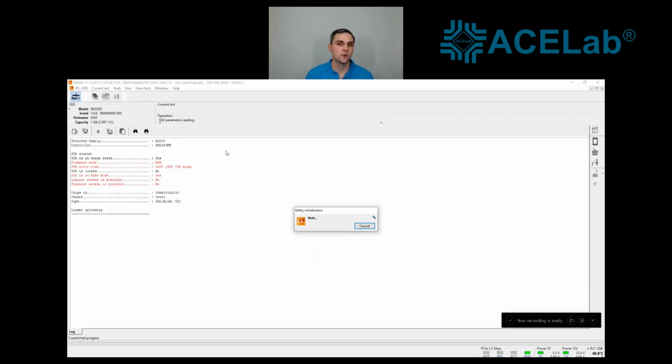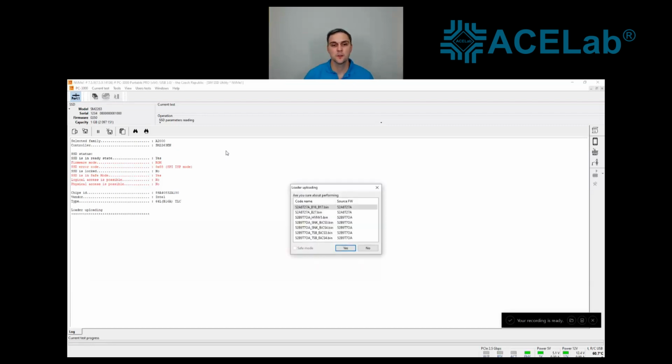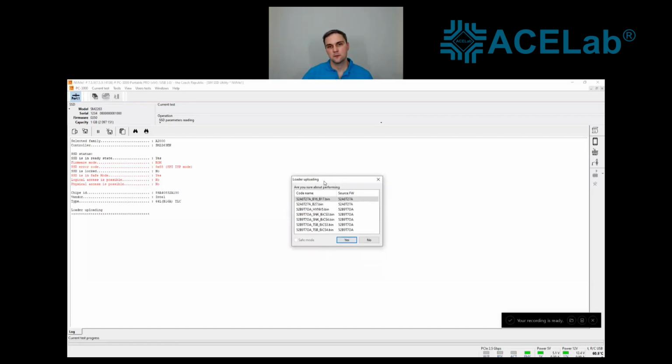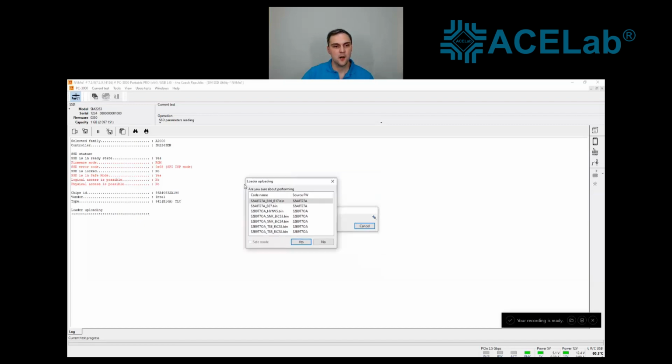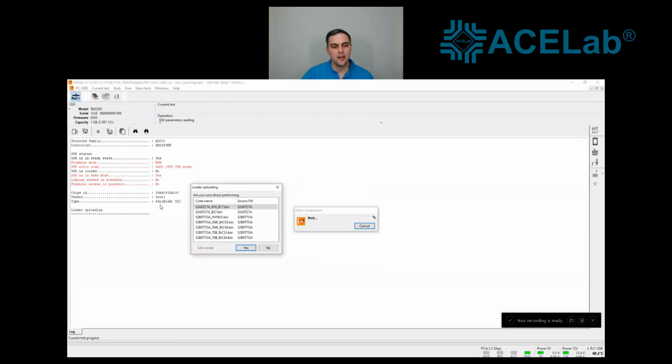Of course, the number of loaders isn't so high as for Silicon Motion 2259XT or 58XT, but all main memory chips, which usually go in a pair with this controller, are presented on the screen. First of all, you can see that our memory chips are Intel based and they have 64 layers with B16A marking and TLC architecture.